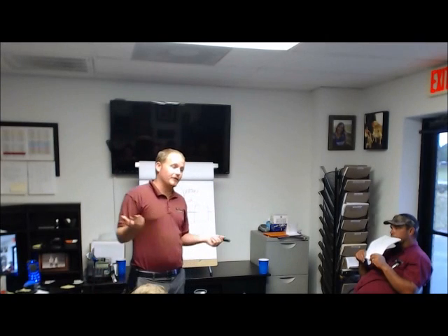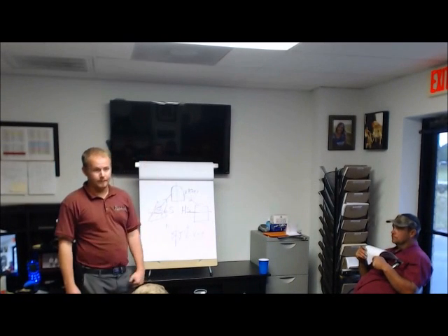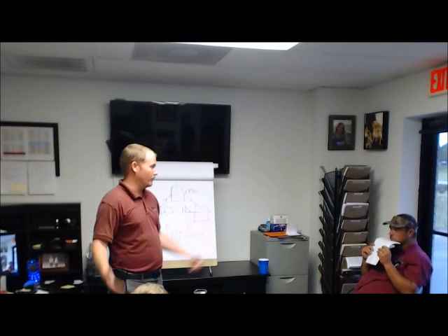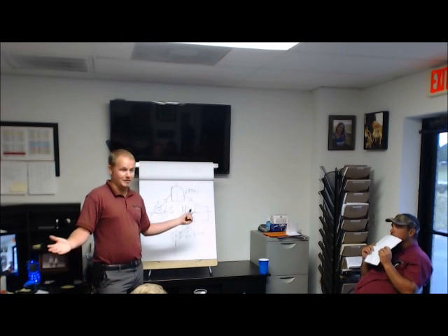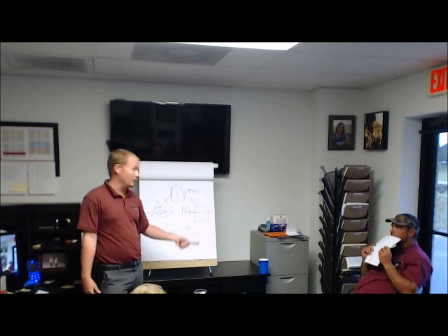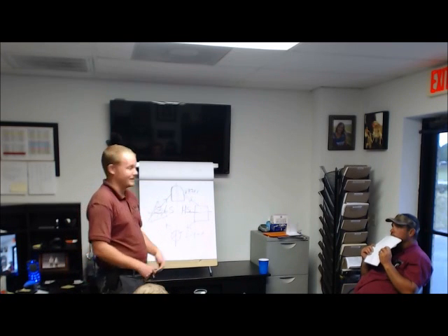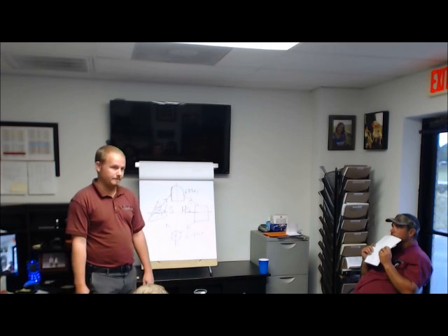If it wasn't for the fact that coils form ice, we would run them as cold as we could. Ice is really the only thing that limits us in direct expansion air conditioning, which is what we work on. That's the only thing that causes us trouble. If it wasn't for ice, we would run coils at minus 10 degrees. But the problem is we build ice, it blocks the coil, and now you're done. Not getting any air through it anymore.